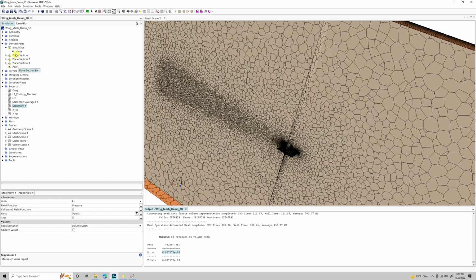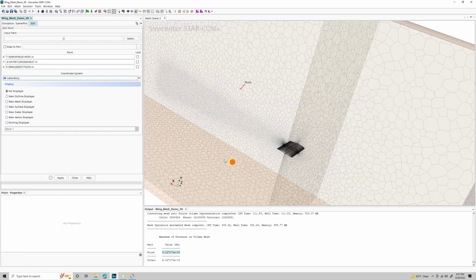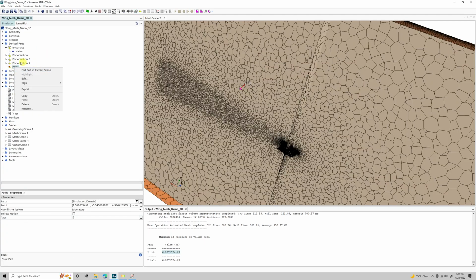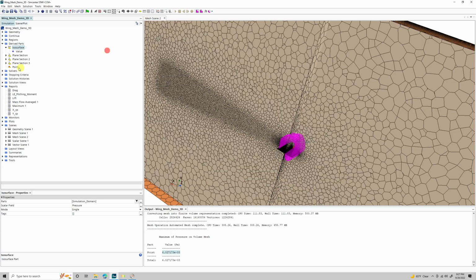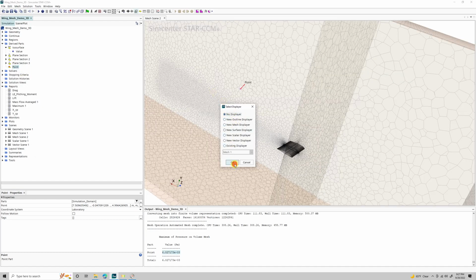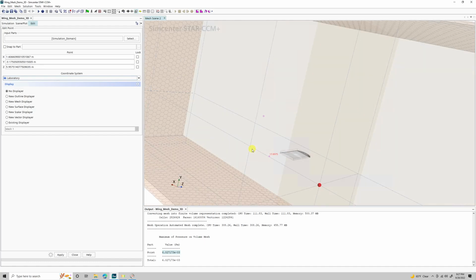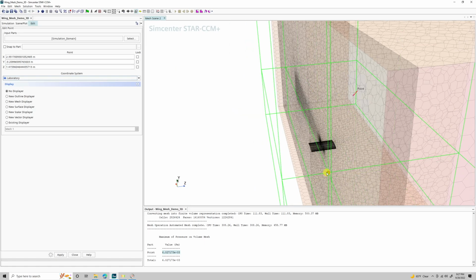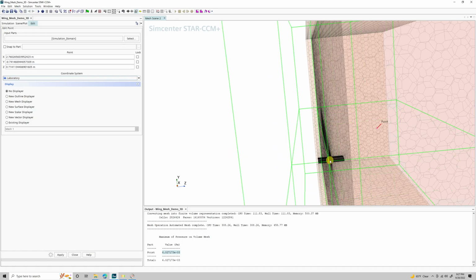Now, if we wanted to know the pressure much closer to the leading edge, we can move this part. Let me walk through that again real quick because I did that a little bit fast. If we want to move it, if we want to move really any of these, we can say edit part in current scene. If you have a geometry scene open, you can edit it with sort of a GUI in the scene. So I'm going to try and move this relatively close to the airfoil. Or wing more properly, because this exists in 3-dimensional space.